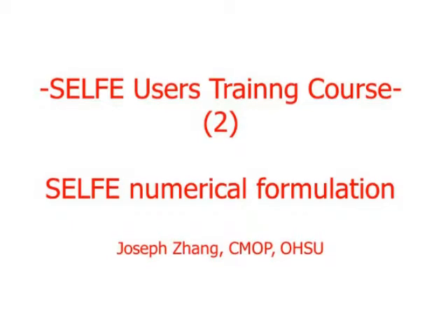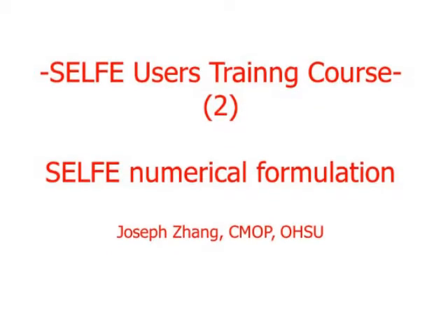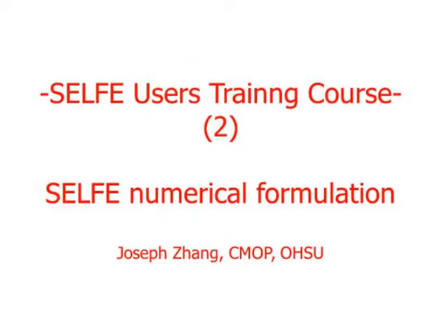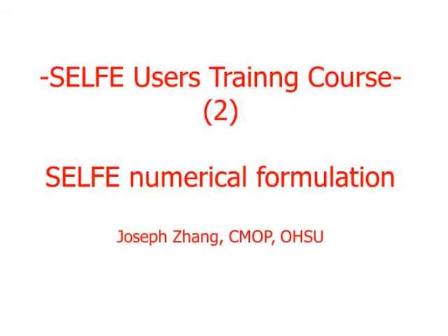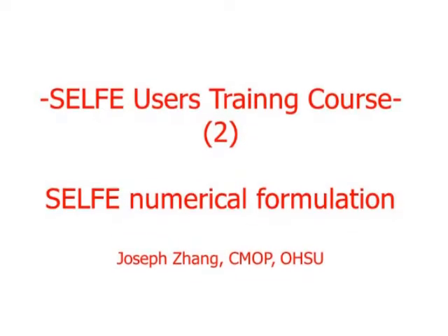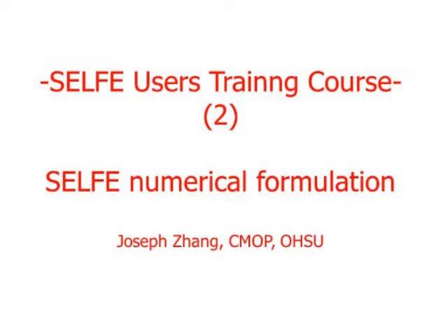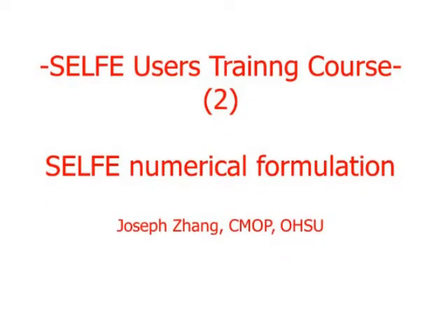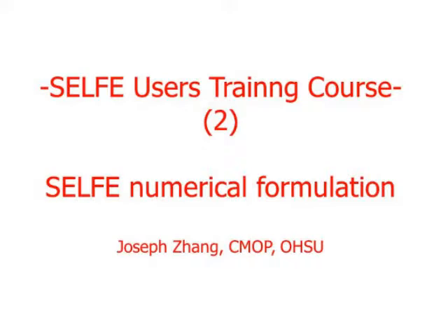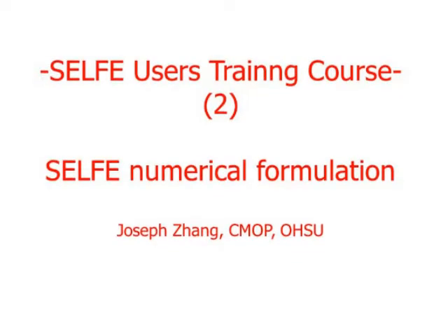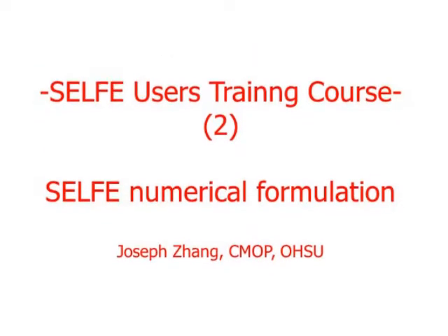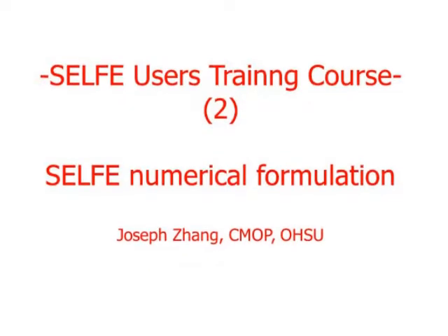If you think about the advection diffusion equations, if you treat the advection terms in the Eulerian sense and use finite volume in a flux form, which I haven't talked about, the finite volume flux form usually conserves mass exactly in a numerical sense.